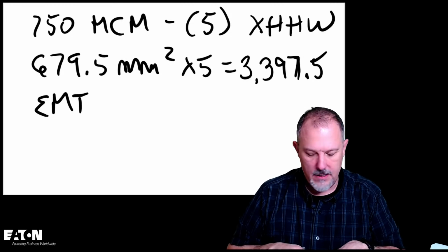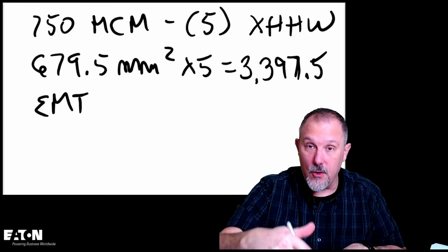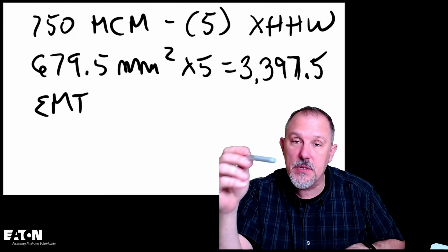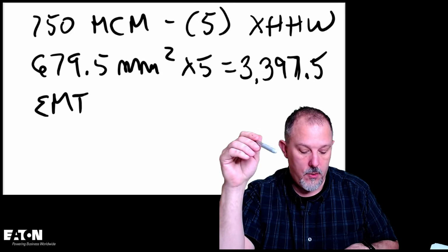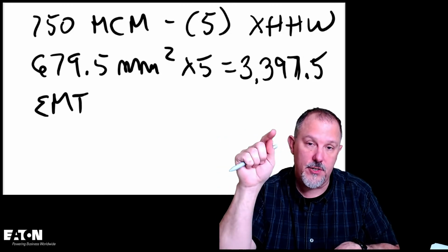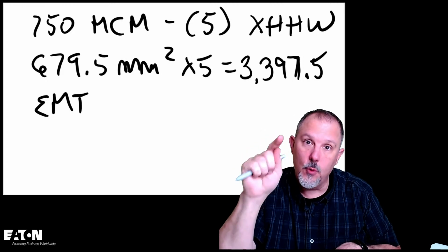Come on. Okay, so what do we know? What's the minimum or maximum percent fill? Maximum percent fill for over 2 wires in EMT is 40%.